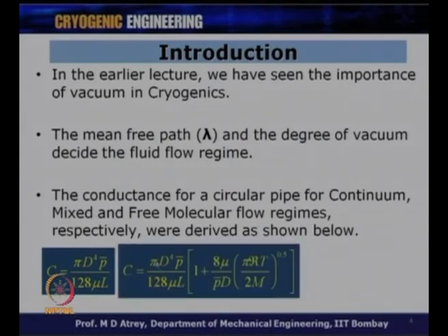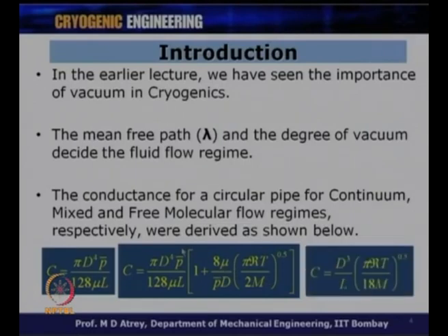Then for a mixed flow, we had a conductance which is a little mixed behavior, with not a very direct relationship to the diameter, but it is inversely proportional to the length, and diameter d to the power 4 is in the numerator, while d is there in the denominator also. And when we come to the free molecular regime, the conductance is proportional to d cube and inversely proportional to L. So, these are the conductances which vary with different diameters, lengths, pressures, temperatures, and of course, the gas property like viscosity, etc.